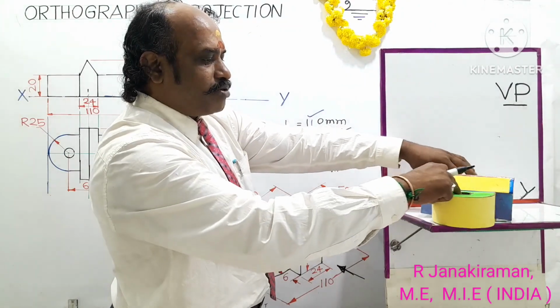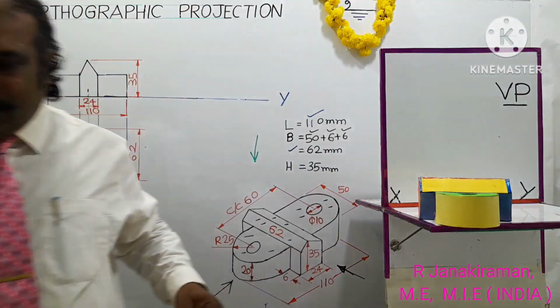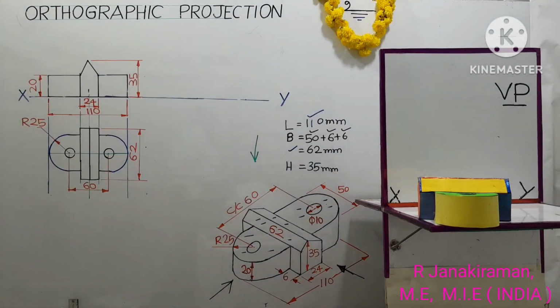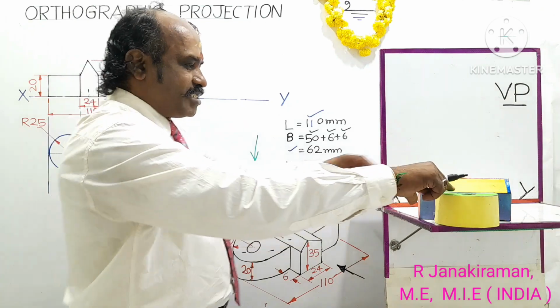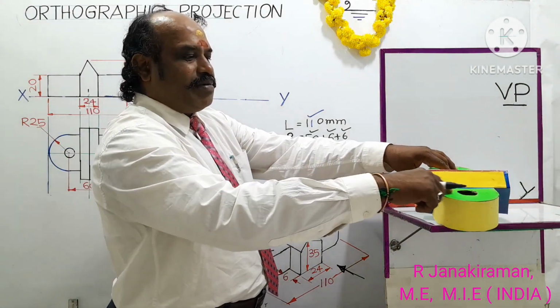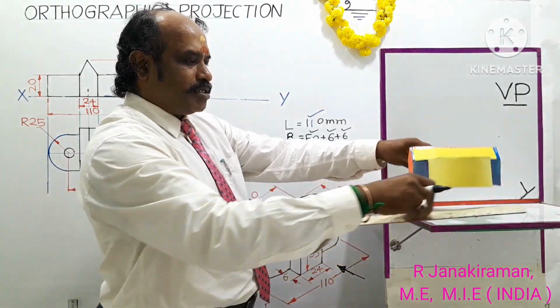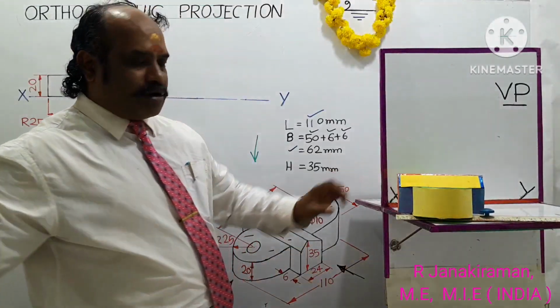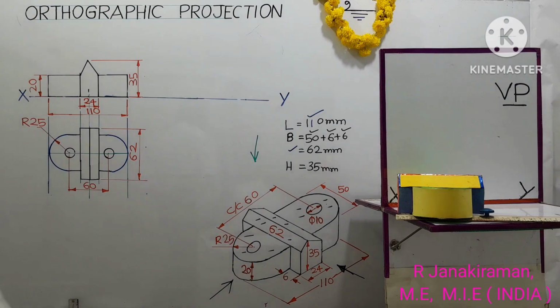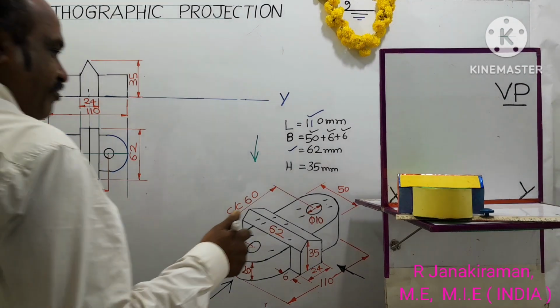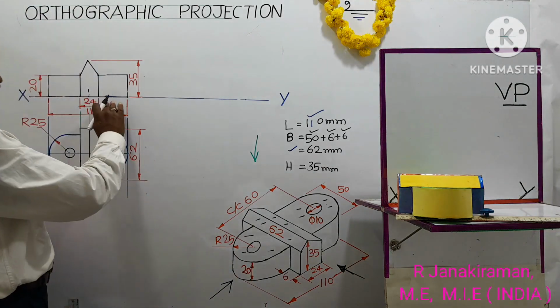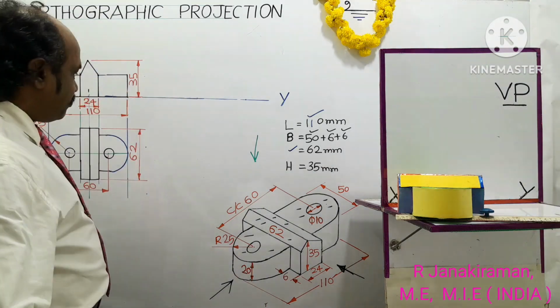So I turn the object so that you can see it in the camera. The view obtained is called the left side view. Moreover, the top surface, yellow, and the green surface will be merged, forming a single top edge of the base. So only breadth and height will be visible in the side view, called the left side view. The left side view shall be drawn on the right side of the front view, following the first angle projection principle.